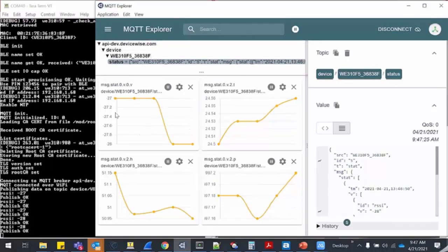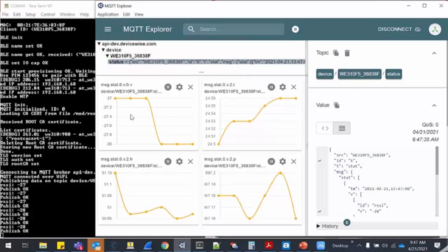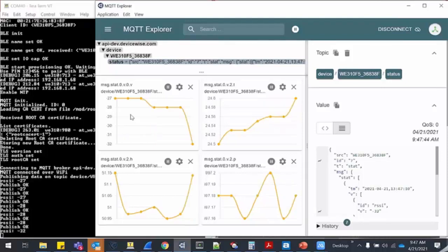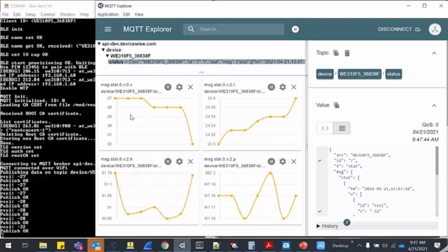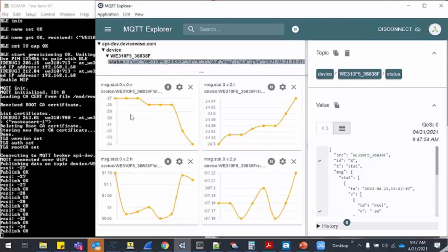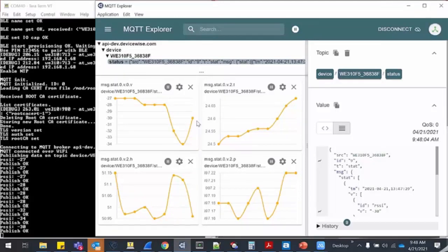And here we are taking the Wi-Fi module's own signal strength, and trying to plot that. So you can see dynamically, if I place my hand on the antenna, your RSSI will further fall down. Now you can see it's fallen from 28 to -32, and if I keep my hand like that, then continuously it further falls down. Yeah, now it goes to 34, and I remove my hand now, and it will come to a proper signal strength. So it came back to 30.